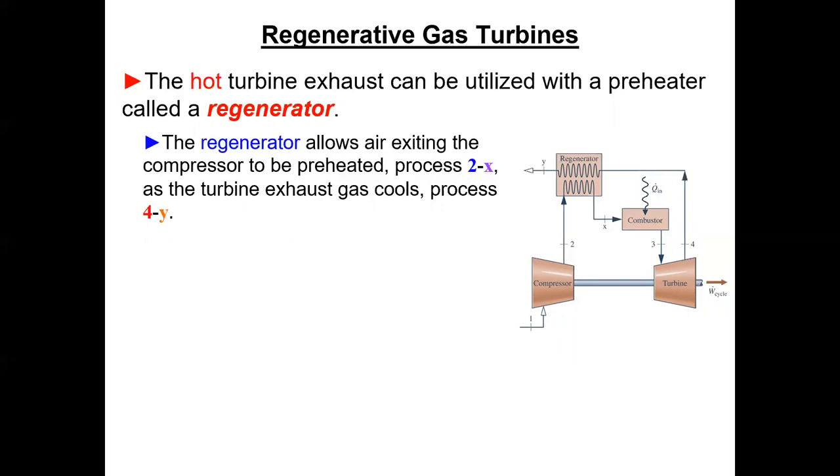Gas control for a combustor is temperature controlled. So T3 will have a set point, and they'll control the gas input, the QN, based on outlet temperature. If we come in at TX instead of T2, and TX is greater than T2, then we just need less gas. It's as simple as that. Put it in hot, use less fuel. And then let's cool it back down. We show the state Y on the exhaust gases going to atmosphere, where we've cooled them down. So pretty simple.